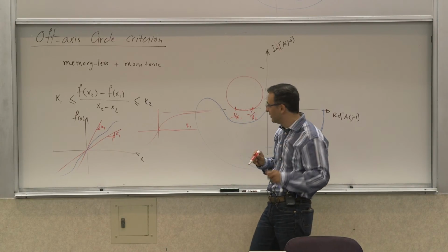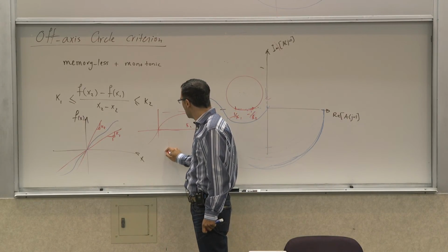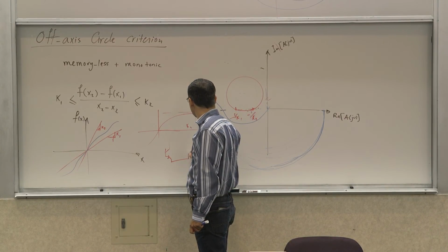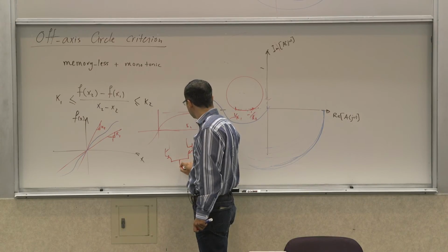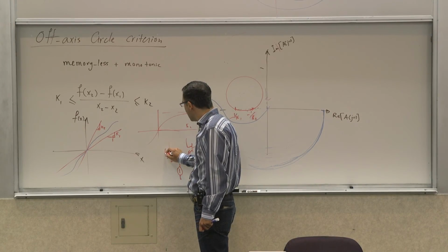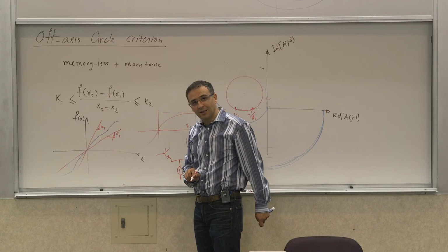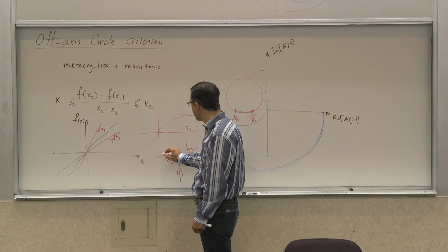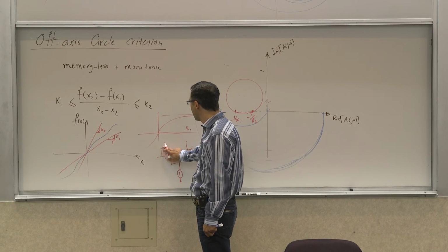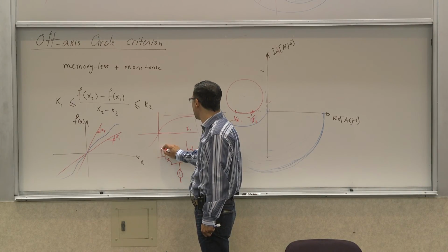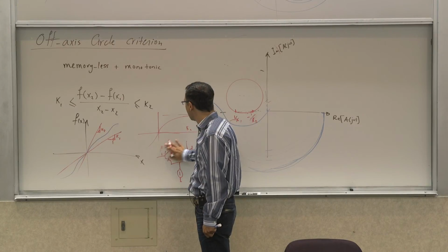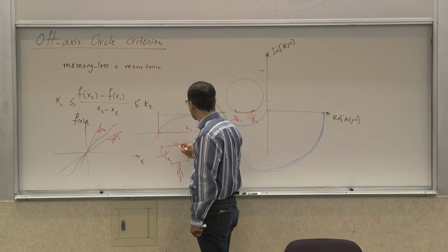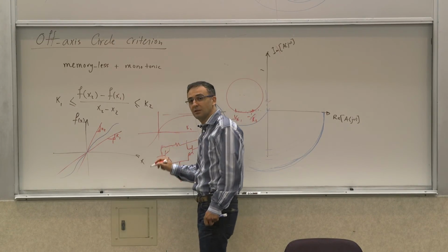However, let's say your nonlinearity can be made with a differential pair with bipolars, for example, right? In addition to that, you can add a little bit of a linear element to it, for example resistors. You can do it in different ways. You can even have an input resistance that couples to the output, or some variation.